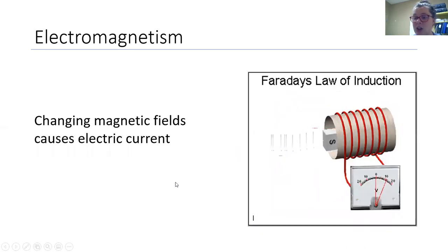Faraday discovered that if we take a magnet and move it through wire, specifically a coil of wire that gives us more wire, moving it inside of a core, the changing magnetic field, so it starts out north and then goes to south here, so the fact that it has to keep moving, can't be stationary, he found you could actually cause a current to occur.